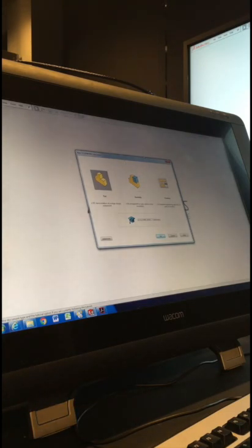So I just want to talk a little bit about the different file types. There are 3 different file types in SolidWorks: parts, assemblies, and drawings. It gives you a bit of a description there. The basic idea is if you're building a car, you don't put all the parts together in one hit. You put the engine together, you put the dashboard together, then you assemble them with the body of the car, so you build it up bit by bit. It's a little bit how parts and assemblies work. You build up your individual parts, and then you might put them together in an assembly file, and then you can put one assembly file in another assembly file, so you can build it up like that.